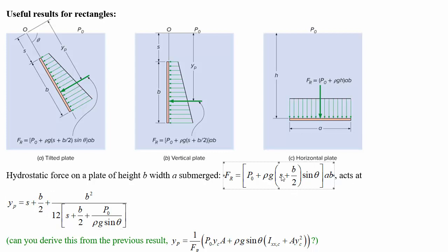Actually, no. Look at what S is in this formula. S is the distance that this side of the plate makes with wherever our origin is, and theta is the angle that's dropped down from the vertical. This horizontal plate that's just displaced a distance under the water doesn't fit into that. It doesn't work with that formula. Fortunately, you can say, wait a minute, the surface is parallel to the surface of the water, so it's all at the same depth, so it's at a constant pressure anyway.